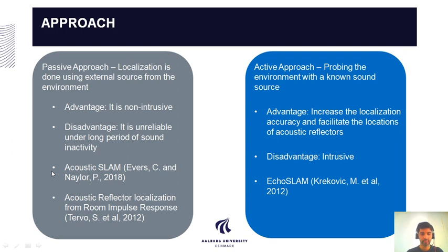In the active approach, however, you probe the environment with a known sound source and you wait for the reflected signals, which gives you important information about the geometry of the room. The advantage of this approach is that it increases localization accuracy, since we are probing the environment with a known sound. The disadvantage of this method is that it is intrusive, but for our application,